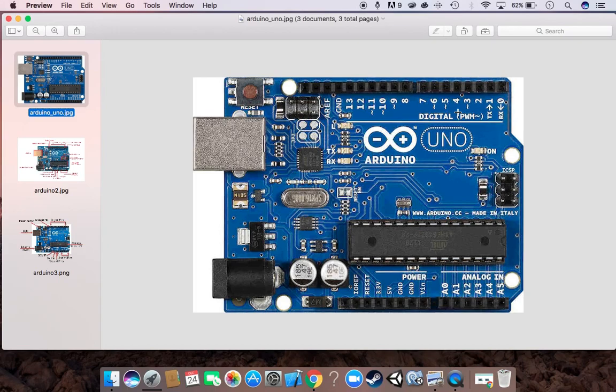Now you want to increase the speed to 20 rpm, that is, you want it to rotate 20 times in 1 minute. So what you will do is connect it to this 10 and 11 or 5 and 6 or 3 and 5, that means to these PWM pins. So you can increase or decrease the speed of a motor using the PWM pins.